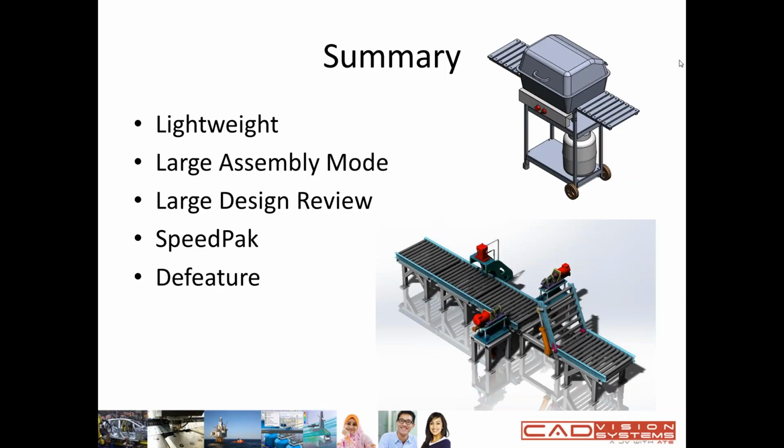Basically, in this webinar, what we will be talking about are the tools: lightweight, large assembly mode, large design review, SpeedPak, and also the feature. All of these you can find in SolidWorks, under the tools option or when you are in assembly mode. About lightweight: if you set the component to lightweight, it will reduce the file size when you open it, and also increase the speed.